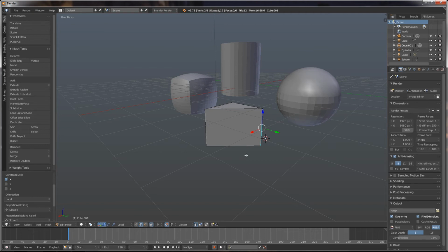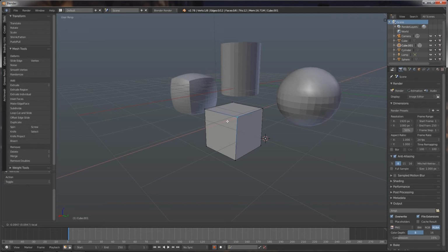Now let's undo that snapping procedure with Ctrl Z. Use the shortcut Ctrl Tab to go into vertex mode. Make sure that Snap is activated and then choose Vertex from the Snap element list. Right-click on the top front vertex to choose it, and then pull it straight back along the X-axis. Notice that when you get close to the back vertex, the two vertices snap together.